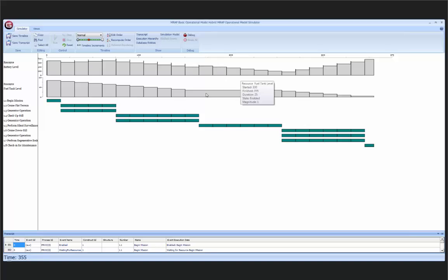So this operational profile may not be satisfactory. Maybe I have to have more gas in there. It would cause me to look at the design and increase the capacity of the fuel tank, or it might say if this is the general operational profile of this vehicle, I really need to have more reserve battery here, and instead of a 900 amp hour battery, I want to put a 1200 amp hour battery and make an operational requirement that says whenever I go out on this mission, I have to have at least 900 amp hours stored in the battery before I leave.